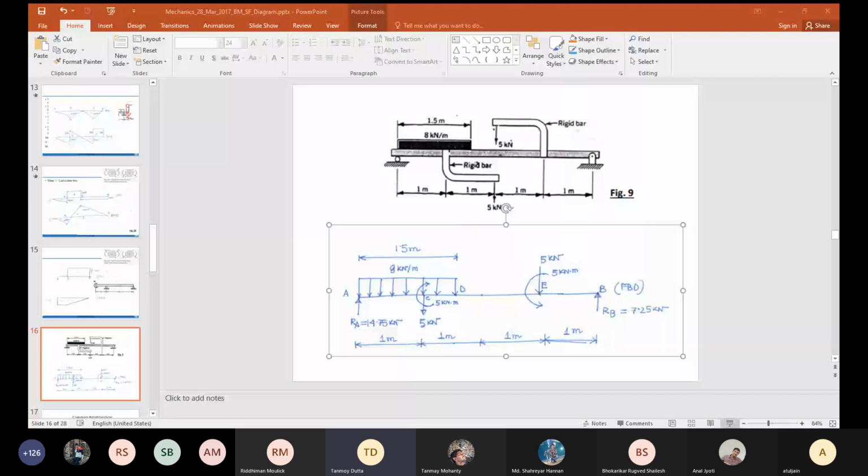Right? Yes, but more than the material, the first tool that you have as a designer is that you will decide the cross-sectional shape. It also depends on the cross-sectional area. Yes, sir. First, you will change the cross-section. If you still cannot get it, then you go to the material supplier and say, I want some other material. Yes, sir. I got it.